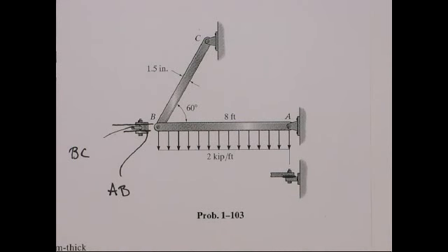So we have to check the maximum shear stress at both pins, and then pick the largest diameter, basically. Or the other way to think about it is we look at which case gives us the maximum shear stress and size both pins accordingly. You could assume that the book is asking for a diameter at pin A and a diameter at pin B. I'm actually not entirely sure which it is. If I were in Solace, I could probably check the solution manual, but let's make that assumption, all right?